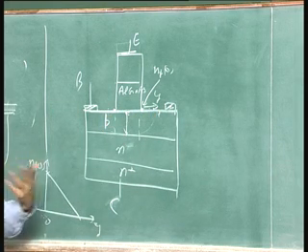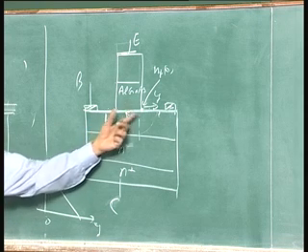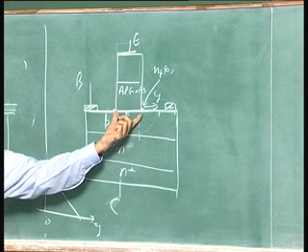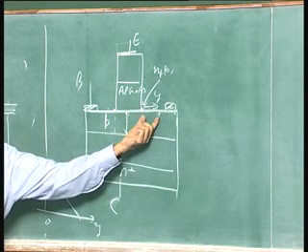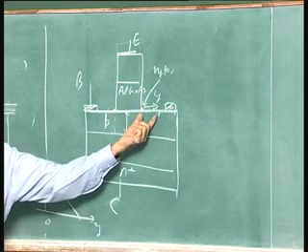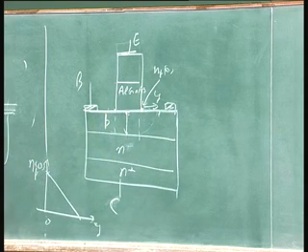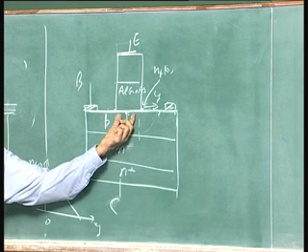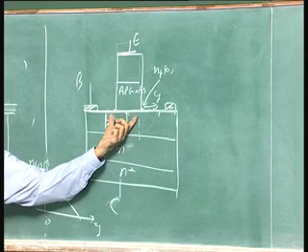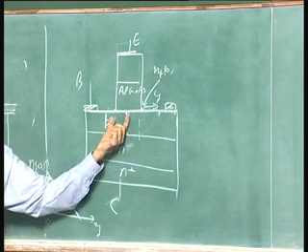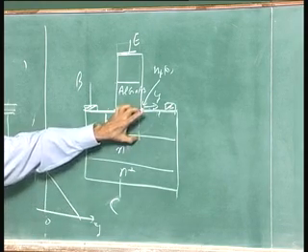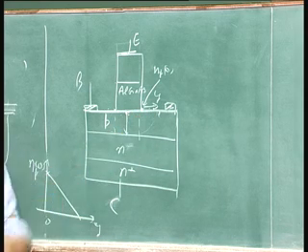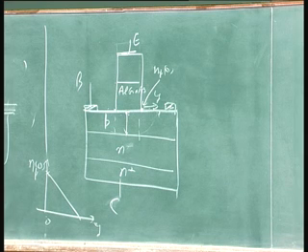Supposing it is a circular emitter of radius R_E, pi r squared is the emitter area, and this area will be pi (r plus that width) squared minus pi r squared. You can see now, if the emitter area becomes larger and larger, this area compared to that will become smaller, because this is fixed by that width. For a given base width, this area is fixed by that. You will see the equations much more clearly.